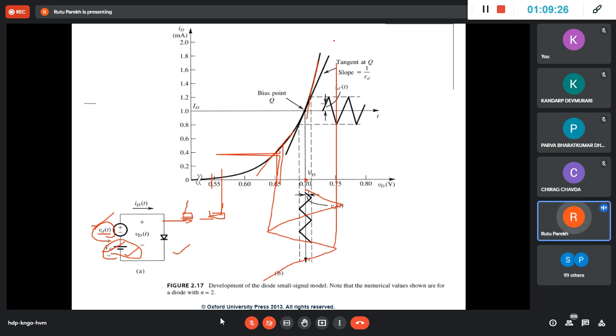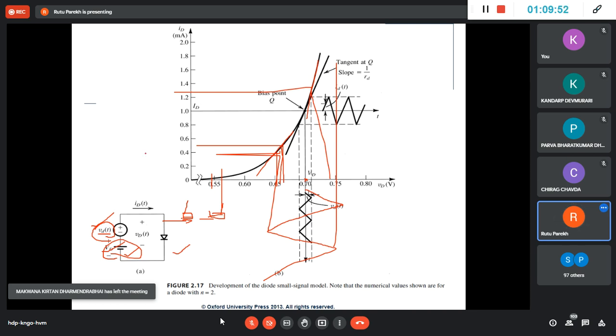This is the nature of the device: every time I turn on the device at this voltage, I will get this current only. If you turn it on and off 100 times at a particular voltage, you will get a particular current only. So if this range is large enough, your current is not going to follow the voltage and it will be non-linear, and then whatever you are processing does not correspond to your voltage.